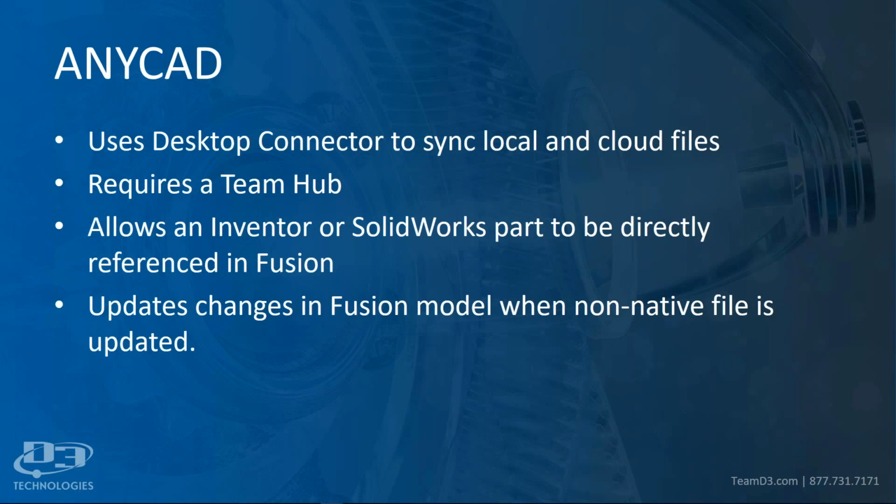So the desktop connector is what you use to enable AnyCAD. Essentially, you're reserving a file location on your desktop that is directly synced to A360. So you have a physical hard location and a quote-unquote soft location on the cloud that are linked. What you put into one will appear in the other if you have an internet connection.